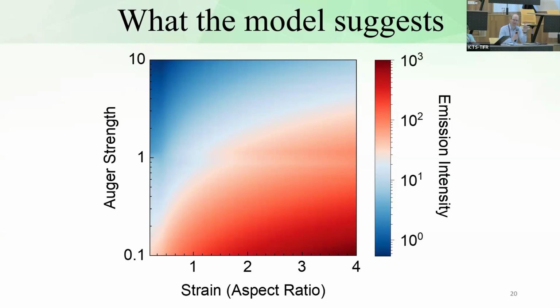It unfortunately doesn't work from an engineering point of view, because for a detector you need to have a good collection. A point defect cannot be a good detector, just because it does not have enough cross-section to collect those photons. This is just an engineering point of view. If you look at the detectors that are available in the market, you get something like 500 micrometer and even bigger than that. They are highly attractive and costlier also, simply because you don't want to miss out on any of the photons that are coming to your system.